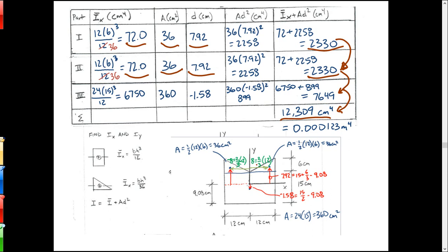Okay. Now what you do with this, we get to this in the strength of materials class. If you want to find the stress, you take the internal moment, which we're about to get to, you get the distance from the neutral axis to the edge of the beam, and you divide it by I, and that's how you find the stress. And then you compare the stress to the material's allowances, whatever the material can handle. That's way beyond this class, so we'll get to that in strengths down the line.